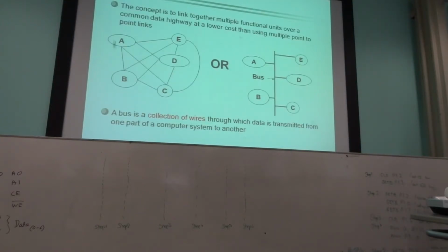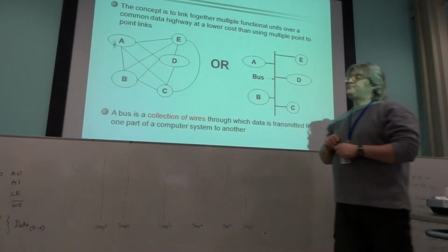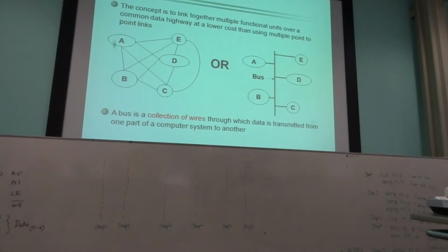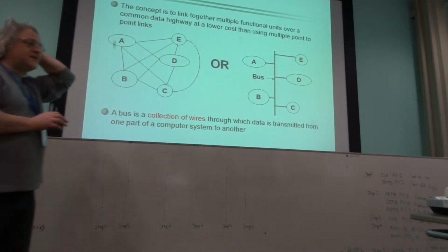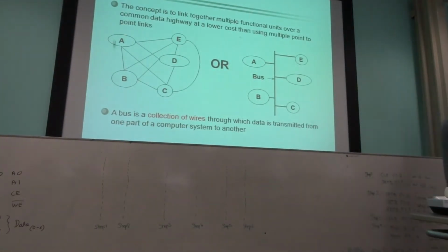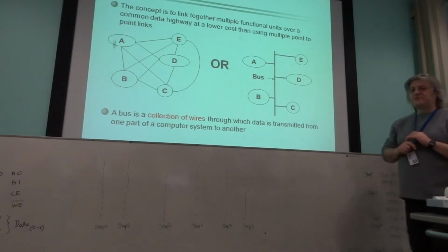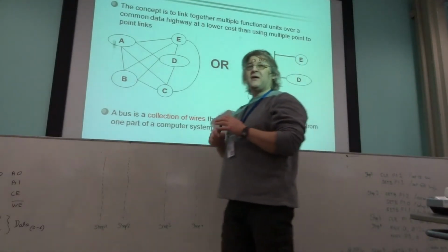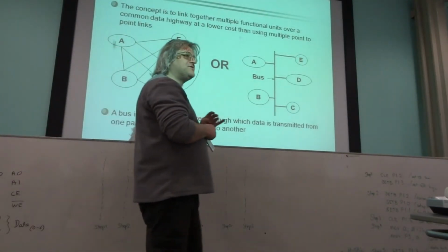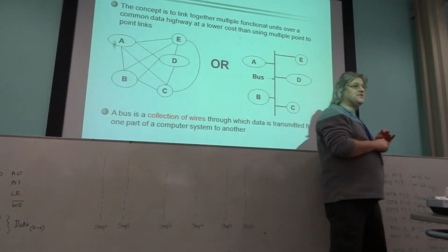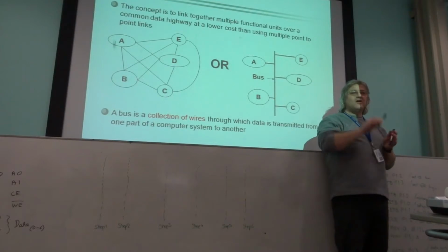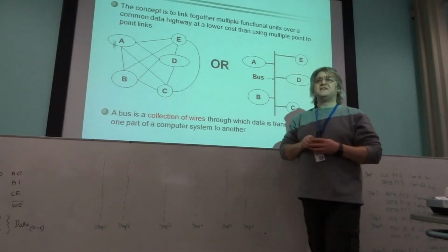That kind of thing is useful, like I say, if you're doing anything in your design and build and you're using a data sheet. It does happen occasionally, the student might come to me and say, well, I connected this to that, but it just doesn't seem to do anything. The first thing I always ask the student under those conditions is, well, show me the data sheet, show me the timing diagram, show me your code. And what I can do is compare the code with what the timing diagram sequence says should happen.